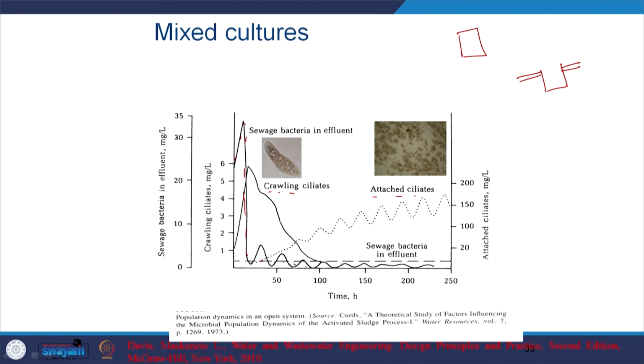Why? Because the kind of bacteria that are going to thrive in your aeration basin are going to eat up, or not create conditions that favor, other kinds of bacteria. For example, one aspect I remember is that fungi and bacteria, which one will grow? It depends on which one has access to more food. Bacteria being smaller have greater surface area, so they can absorb the food faster. Not the case with fungi. So, over time the bacteria are going to thrive. That is one aspect to keep in mind.